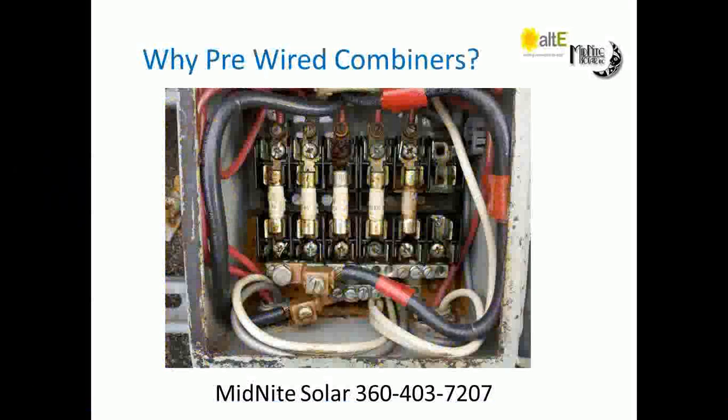AC coupling on Sunny Islands requires either SMA that will frequency shift or special considerations. No, I didn't mention that, but the Sunny Island itself frequency shifts. Frequency dithers like the Xantrex, I'm sorry. So if you have a Fronius inverter, and Fronius is a bad example because I think they void your warranty if you're AC coupled. But if you have an inverter out there that is not a Sunny Boy inverter, and you hook it up to a Sunny Island, the same thing will happen as it does on the Xantrex. When the batteries get full, the frequency will dither, it'll kick the inverter offline, the batteries will drain back down a little bit, and then it comes back into line and everything is good again.